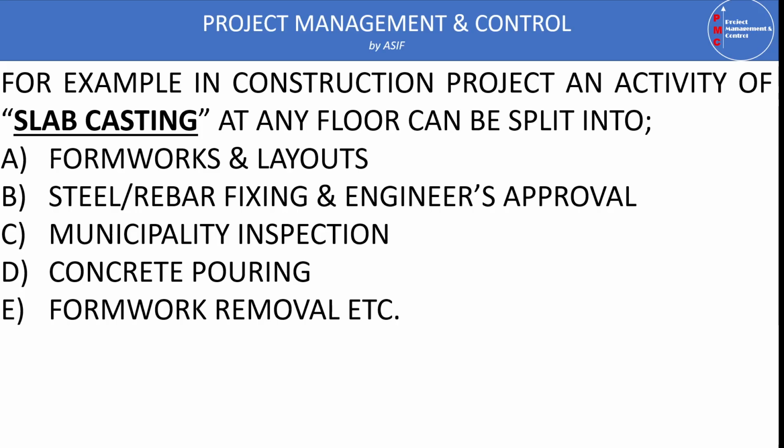It will make our project schedule lengthy, and it is sometimes not advisable to add such minor details in our schedule if it is agreed by the client or engineer. These details or definitions we can assign as activity steps. So it will reduce the number of activities in our program, and then we can assign the weight factor for all these activities.